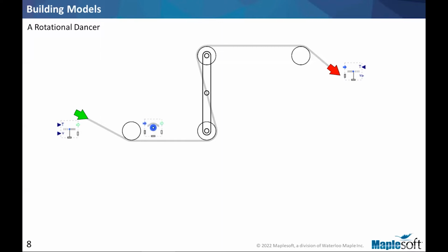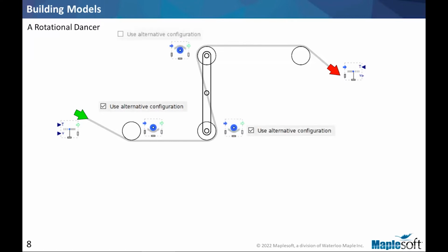Then we would need rollers. As I said, there are 4 rollers here. So there's a roller component that one would drag. And this slide is also similar to our canvas in our modeling tool, MapleSim. So each of these rollers, you have the option to say the web goes below or above. So you can quickly arrange the model as you would require.